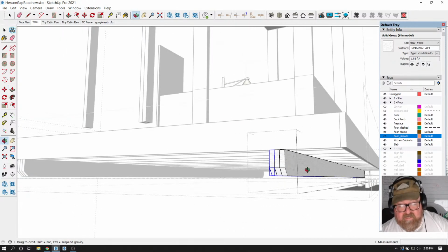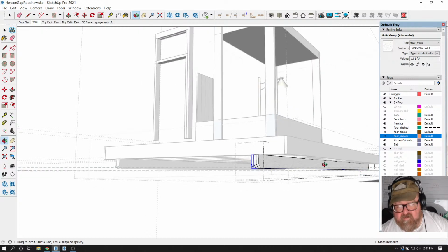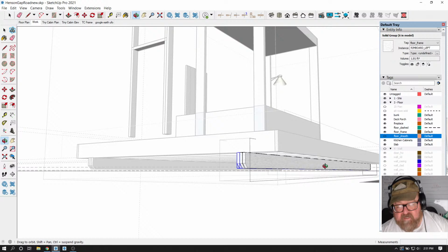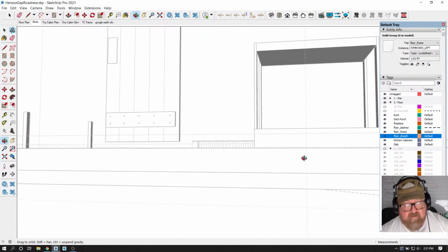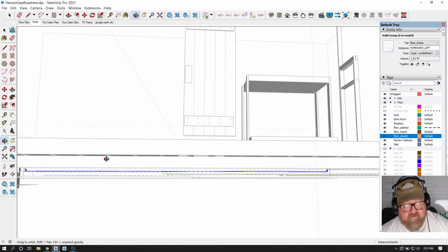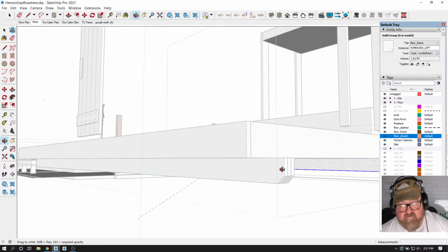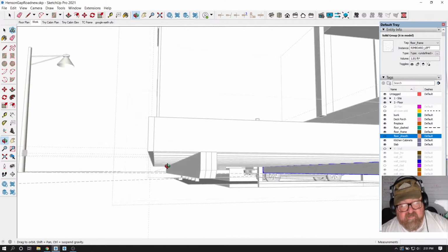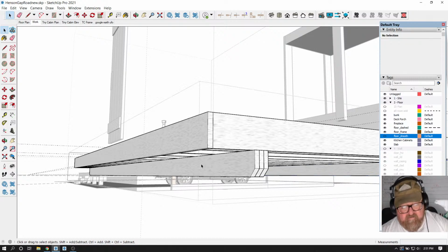I'm going to bolt it together with lag bolts. I'm not just going to nail it, okay? And then what it'll be is two 12-footers starting off, right? So you have a joint right in the middle, and then the next row will be a 12-footer in the middle, spaced out, and it'll have two 6-foot pieces on the end. And then the final layer will go back to the two 12s from each end. So all the joints in the beam will be staggered, and then they'll be bolted together.